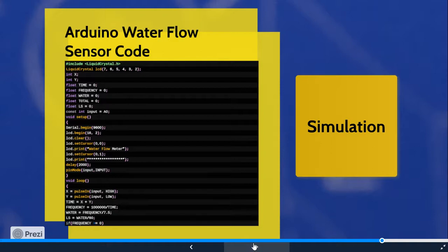The current time and loop time assure that for every second of the loop, the flow frequency is used for calculation of flow rate and volume. Once the calculation is completed, the flow frequency variable is set to 0 and the complete procedure starts again from the beginning.